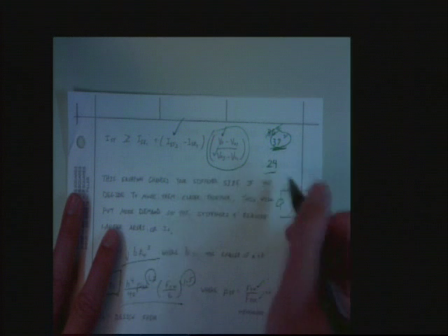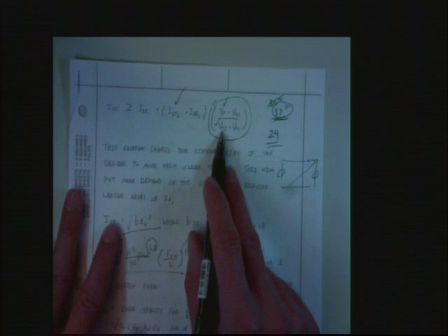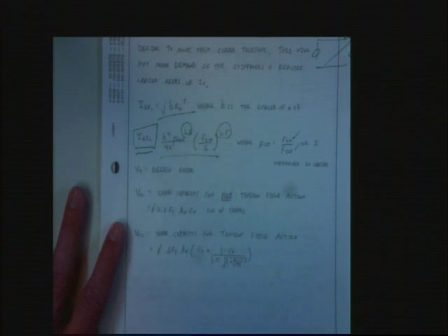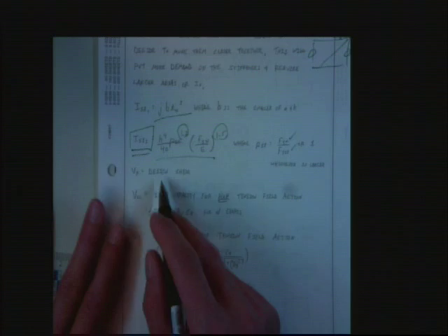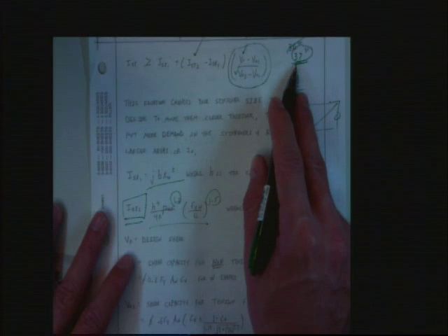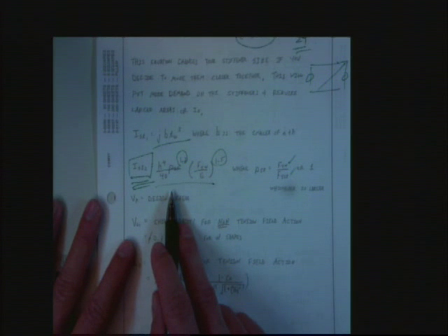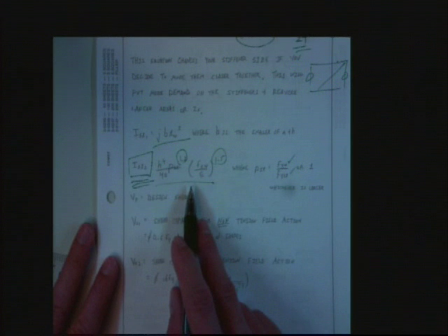Now, if for some reason you back it off, so you're going to jack V sub 2 way up, make it a lot larger than what you need, that will change things. Does that make sense? Oftentimes, if you took nothing else away from what I just said, if you choose your stiffener spacing closer to the requirement, this equation dictates your minimum stiffness. You don't have to calculate anything else. And not calculating things is nice.